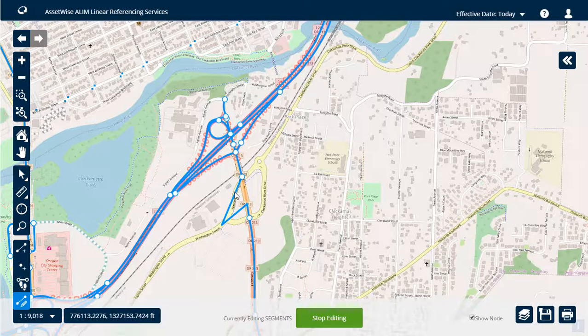As mentioned, the Radial Menu is context sensitive, meaning that if you click on a datum, the menu displays several options, while if you then press Ctrl and click on a different datum to select them both, a different menu appears. In this case, two connected datum features are selected, so the only available operations are Merge and Shared Reshape.